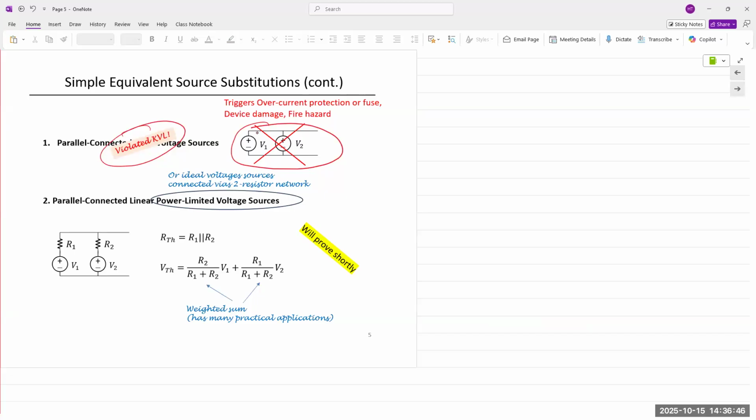Here's the thing. Current always flows from high potential to lower potential. So if you have a 3 volt battery connected in parallel to a 1.5 volt battery, the 3 volt battery is a higher potential. So it's going to start supplying energy to the other battery. Okay. If that is not controlled, then a reaction takes place where a lot of energy is expended, a lot of heat is generated, and because of the generated heat, it could cause a short circuit, cause a fire. Okay, so that reaction must be controlled.